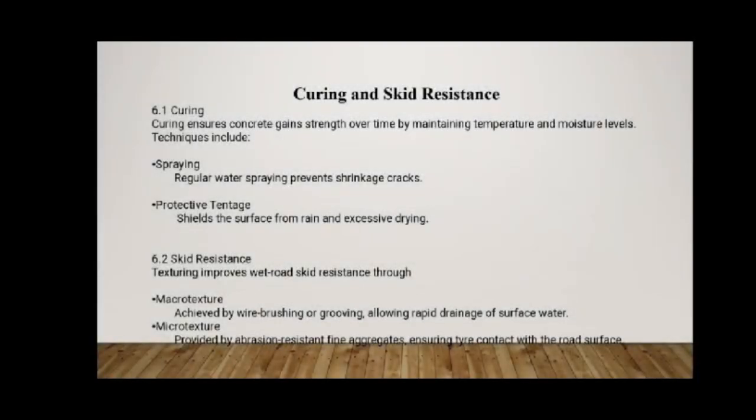Next is curing. First is spraying. What spraying does is prevent moisture loss of the concrete and ensure proper hydration. If the concrete dehydrates, its strength and durability decrease, and it becomes vulnerable to cracks. Next is protective tents. Protective tents allow the concrete to cure properly.